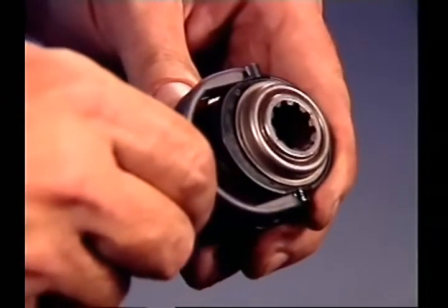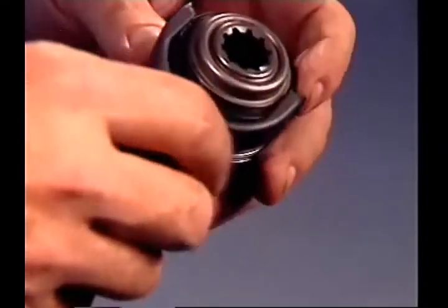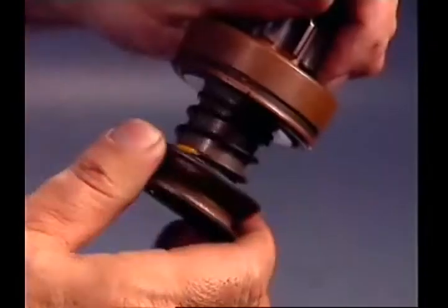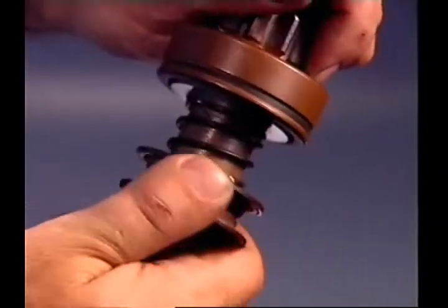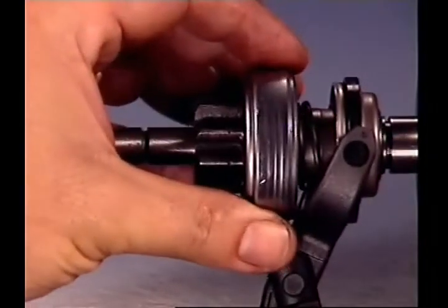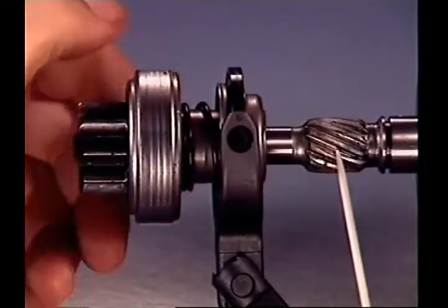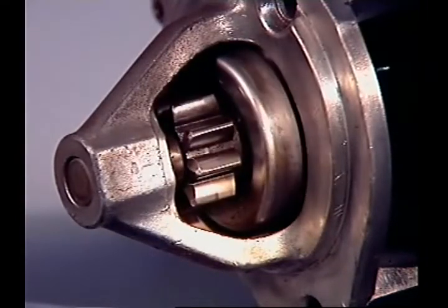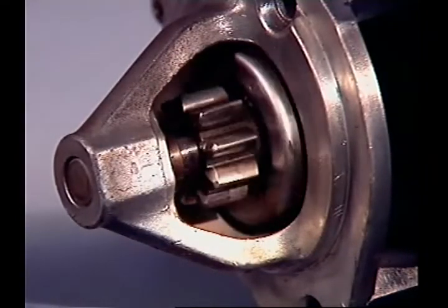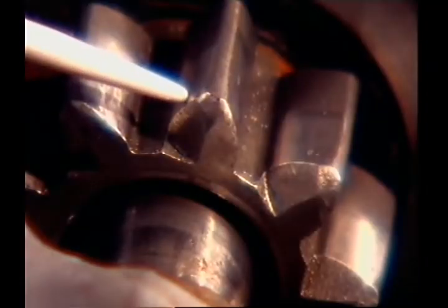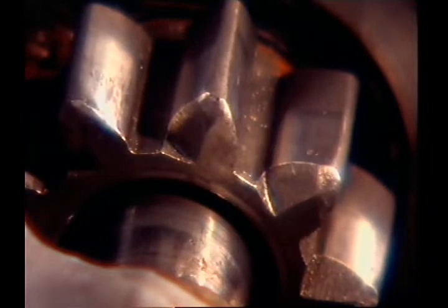The fork locates in a guide ring on a pinion driver, which is coupled to the pinion via a roller-type overrunning clutch designed to transmit drive in one direction only. The pinion driver is mounted on a helix machined on the armature shaft to form a very coarse thread. This allows the pinion driver to rotate slightly when it is moved towards the ring gear, and this feature, together with a chamfer on the leading edge of the ring gear and pinion teeth, is designed to assist meshing and